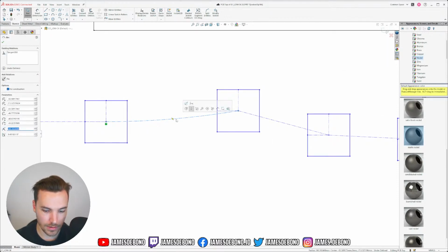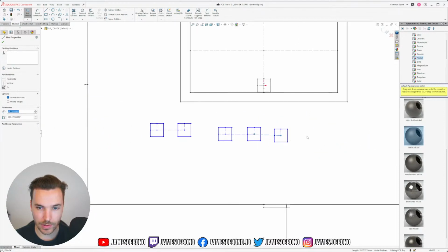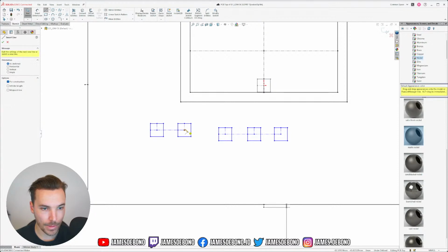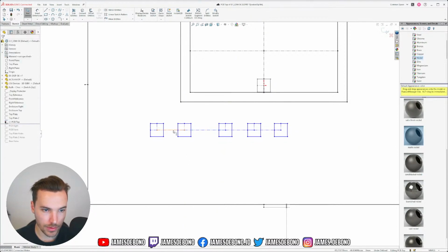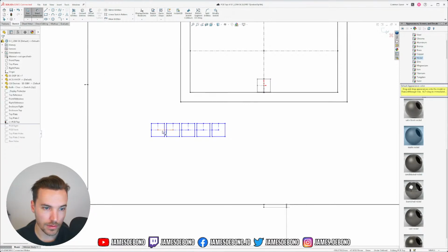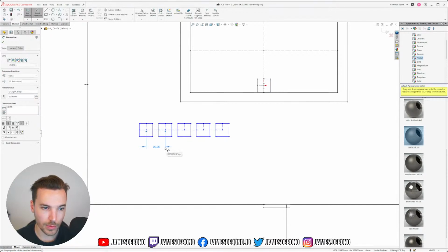Is that an arc? Connect them all with these construction lines, make them horizontal and also make them equal so I have an even spacing between them, and give them a dimension. Let's say they're 20 millimeters apart.